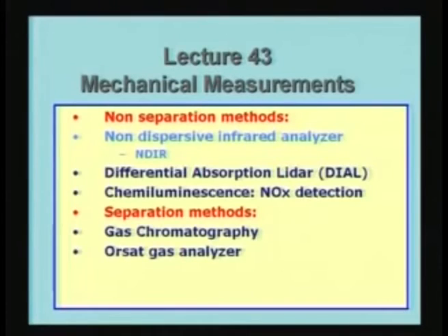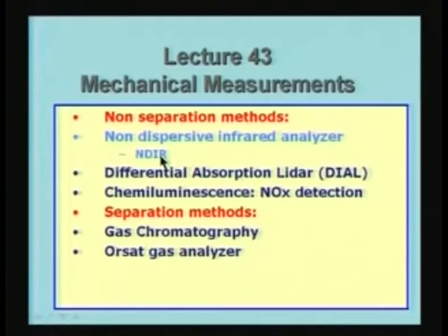So, this will be lecture number 43 on our ongoing series on mechanical measurements. Towards the end of the last lecture, we were looking at measurement of concentration of gases using so-called non-separation methods. In the previous lecture we covered the non-dispersive infrared analyzer, which is a very useful instrument used in day-to-day laboratory practice for measuring especially exhaust gases from IC engines.